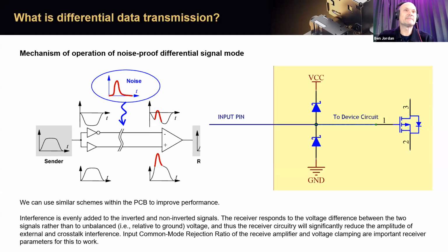It's a capacitive load, and to protect the silicon device, it's pretty much invariable that they have Schottky barrier diodes or some sort of TVS diode built into the silicon that will isolate inputs, or not isolate them, sorry, wrong word. It will short inputs to VCC for input voltages that exceed VCC plus that forward voltage drop of that Schottky diode, which is usually about 0.5 volts.